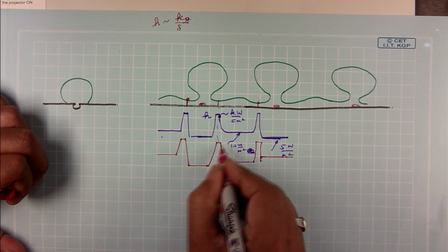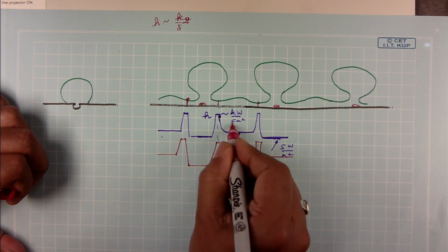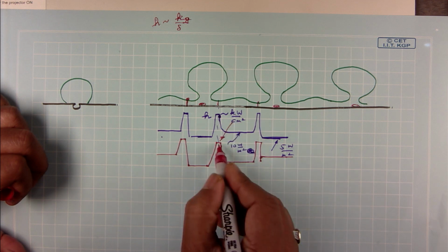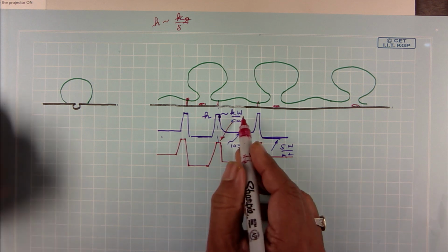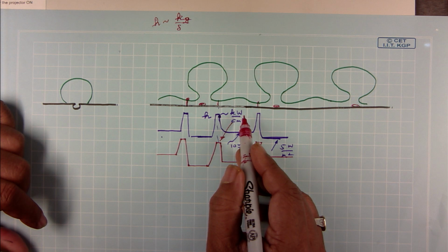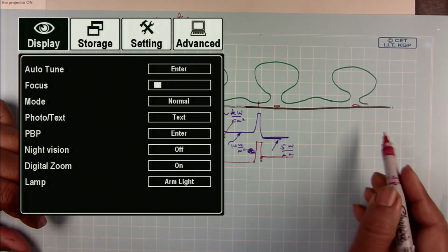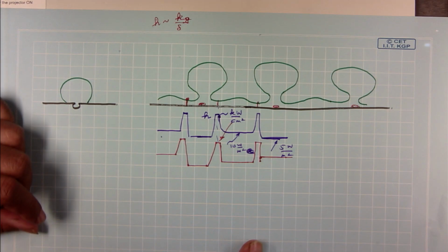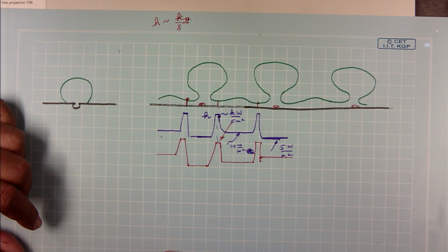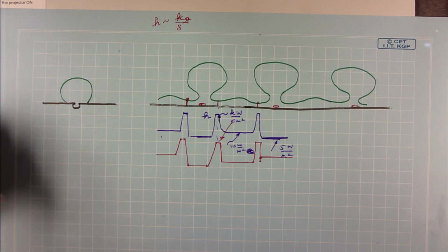So, the peak heat transfer is going to be of the order of kilowatts per centimeter square or 10 to the power 4 watts per meter square. So, effectively the rest of the surface is insulated, is not it? And I have these zones where it is like a delta function of very high heat transfer. That is how film boiling operates, all right.